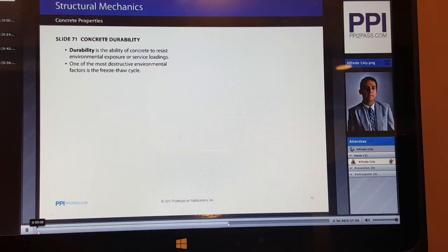we have added reinforcement to handle tension better. However, if there is not enough reinforcement to handle the freeze-thaw cycle, we can still see some cracking and spalling. Now, that cracking and spalling can allow moisture to get to the steel bars. Therefore, those steel bars will then start to corrode.